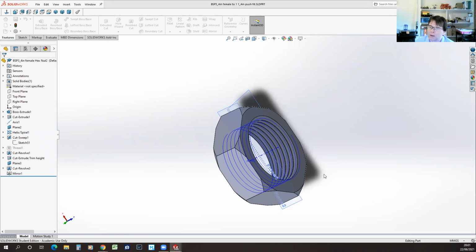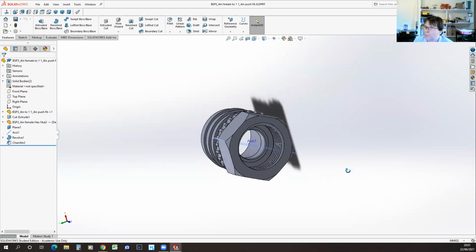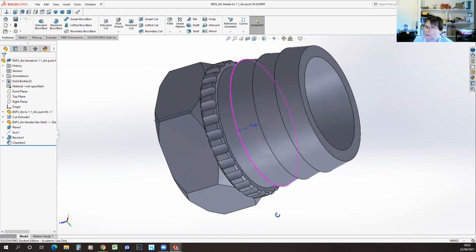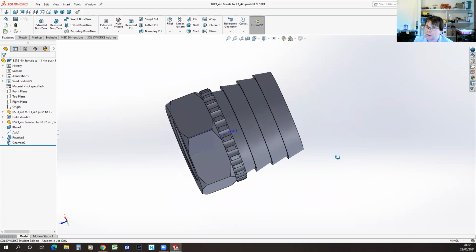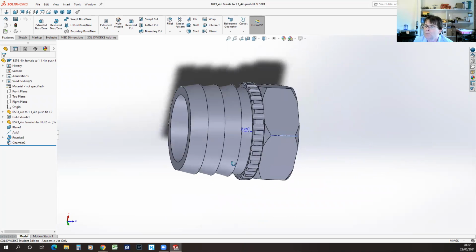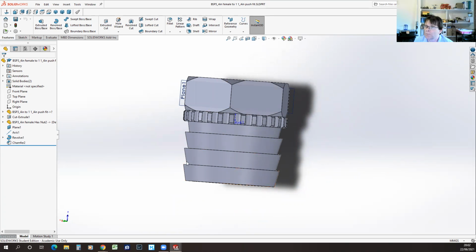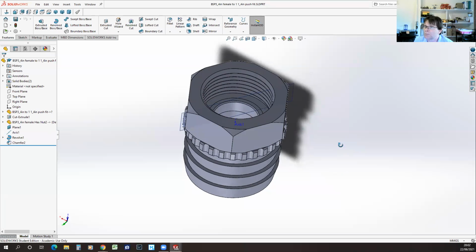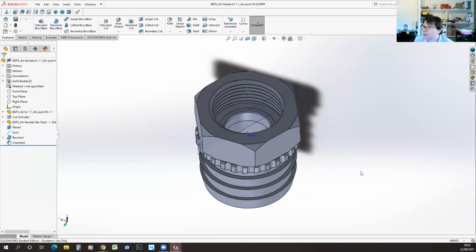So I created this threaded nut part and I joined it onto the push fit connector that I designed separately. And that was the thing that I 3D printed in the end. And this thread 3D printed absolutely fine without any support material. So I designed this with sufficient tapers. I printed it this way up, so that was on the print bed, and so these overhangs were small enough that there was no support material needed. And so straight off the print bed, I ended up with a completely working thread and was able to connect my hoses up, and it worked very well.